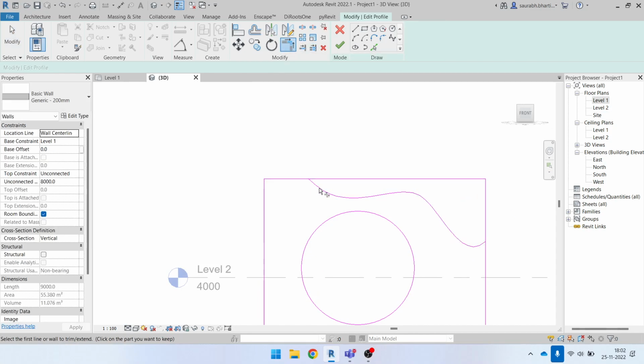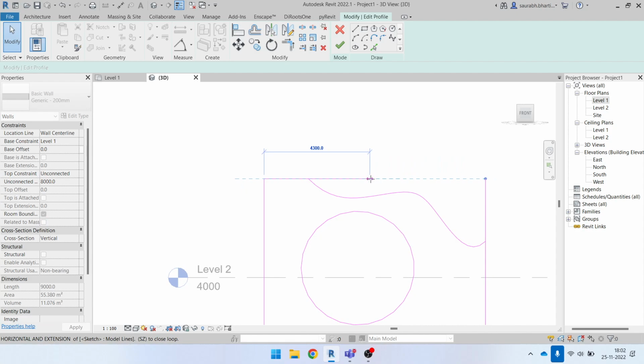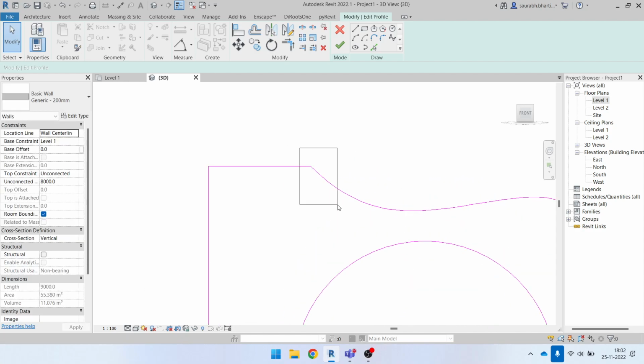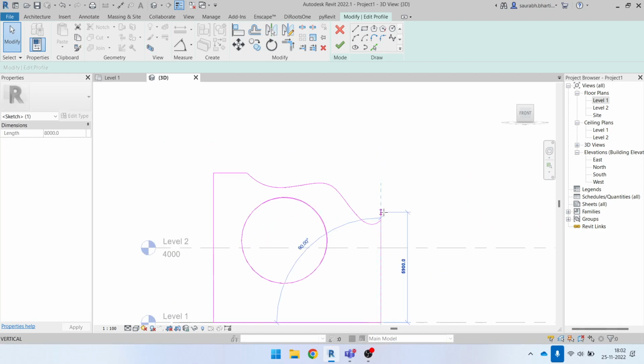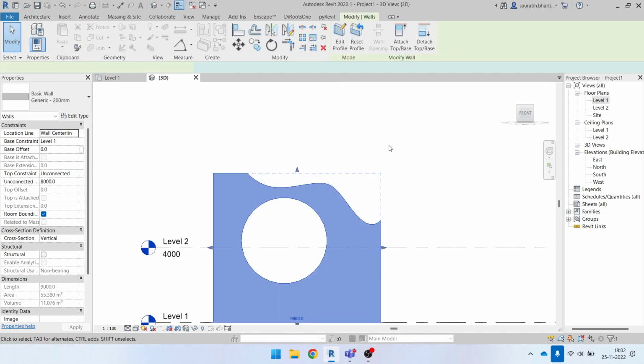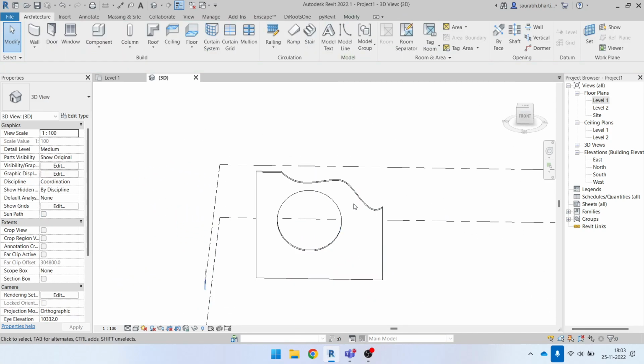This is not useful when you are using a spline. So if you ever use a spline, what you have to do is get this back to the origin of the line manually like this, and now you can see it got attached itself. You can do the same thing here, and now if I press OK, you will see this is a deformed wall that we have drawn.